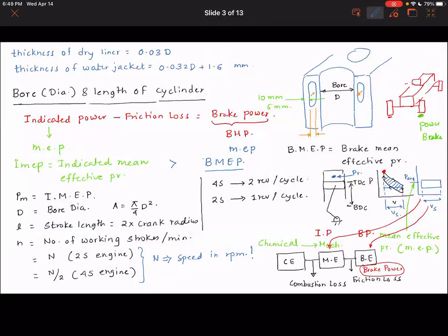What would happen when the quality of the incoming charge is reduced? That means you will not reach the pressures that you would reach in the ideal case. Your mean effective pressures would be low. Lower mean effective pressure means your power will be low, but that will drop your cylinder temperature down immediately, and that may prevent the cylinder and piston from burning or overheating.